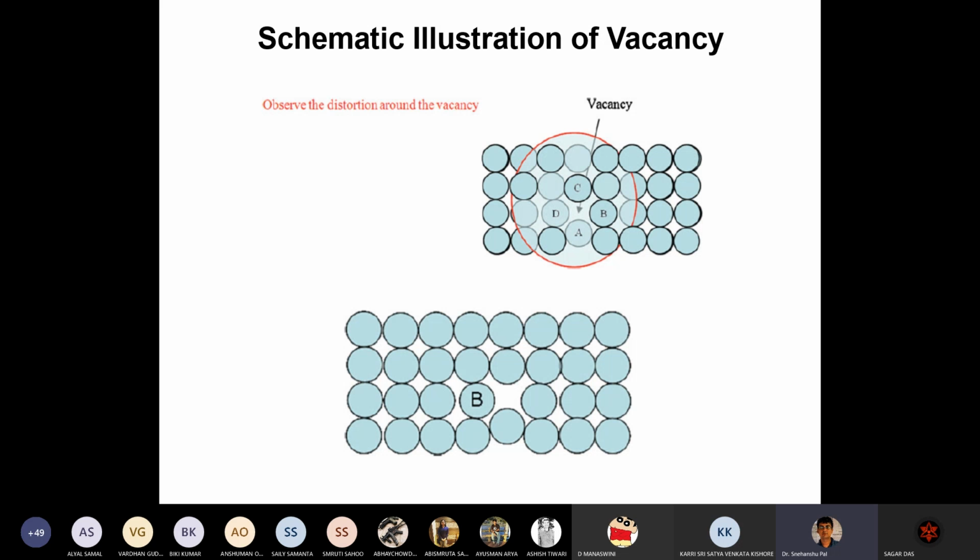If you go for further classification, especially suitable for semiconductors, then you can refer to the defect as intrinsic, which is present in a pure material at equilibrium, or extrinsic, induced by doping or alloying, or by the presence of extended defects like grain boundaries or surfaces. Those are the two kinds of defects you can get, intrinsic and extrinsic, in electronic materials or semiconductors. In this way, there are two kinds of defects.